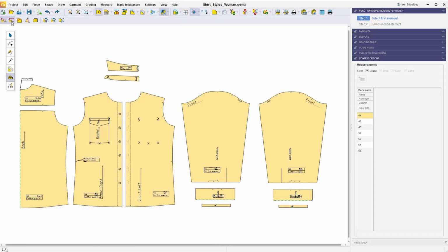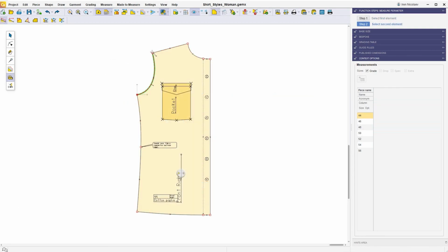For a straight length measurement, select the type you need, select the piece you want to measure, click on the start point and on the end point. The value will immediately be visible along the measured section, but also on the right part of the screen, in the activity area. You should know that all measurements must start and end in a point, or any other kind of technical element such as notch, internal hole, button, or internal lines and shapes.